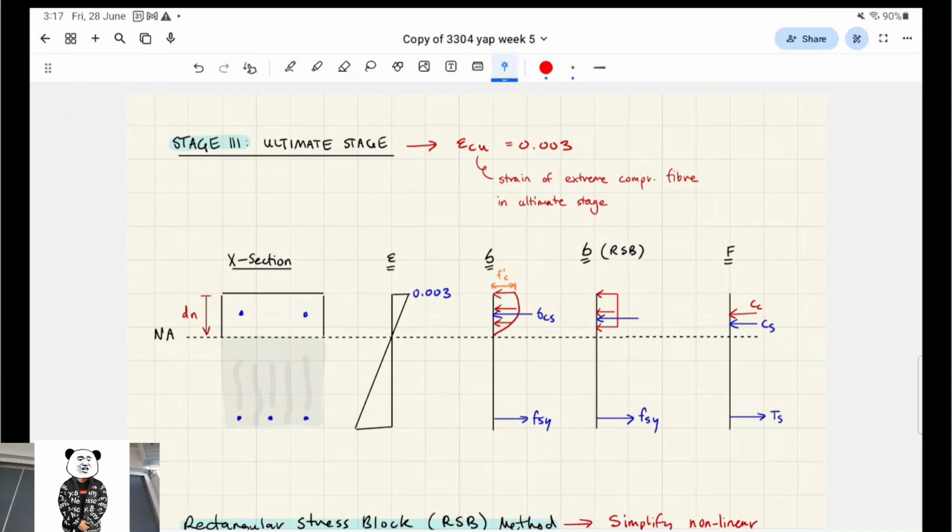for the types of beams you'll have to derive, right? So you might have one layer of compressive steel and one layer of tensile steel, right? But you could also have two layers of tensile steel, two layers of compressive steel, or zero layers of compressive steel, you know what I mean? So every section is going to look a little different. You could also have a T-beam, which we'll be talking about in a bit, but the idea is we just learn the skills and you can apply it to any section of reinforced concrete.